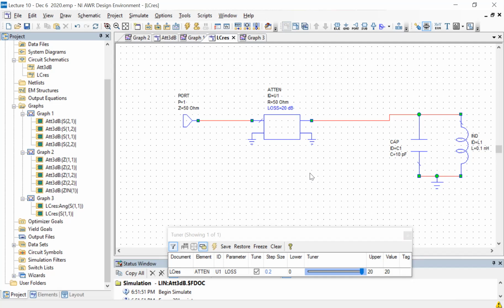Sometimes those cables are part of a measurement setup, so you want to account for that, or sometimes you want to remove the attenuation of the cable to know what's going on in the fridge, for example. So the bottom line is, if you're only interested in transmission as a function of frequency, then this is a reasonable thing for simple devices like attenuators and filters.